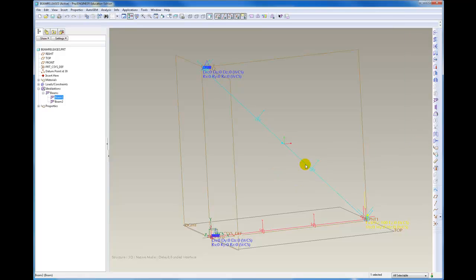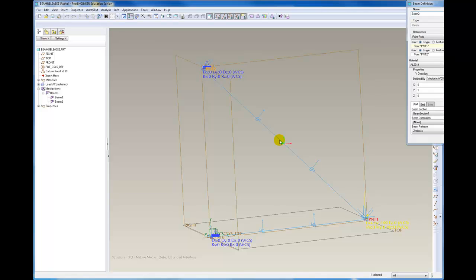OK. And then I'm going to select, let's see if I can double click on this beam. It did. And the red one, point 1, is a Z release. And I'm going to turn it off. And then I'm going to go to the other end and turn it off as well because it was ineffective. This Z release and this Z release was ineffective. I only really need one of these two beams coming into this joint to have a Z release. And I've left the Z release on the lower beam. I've now removed all Z releases from the upper one.